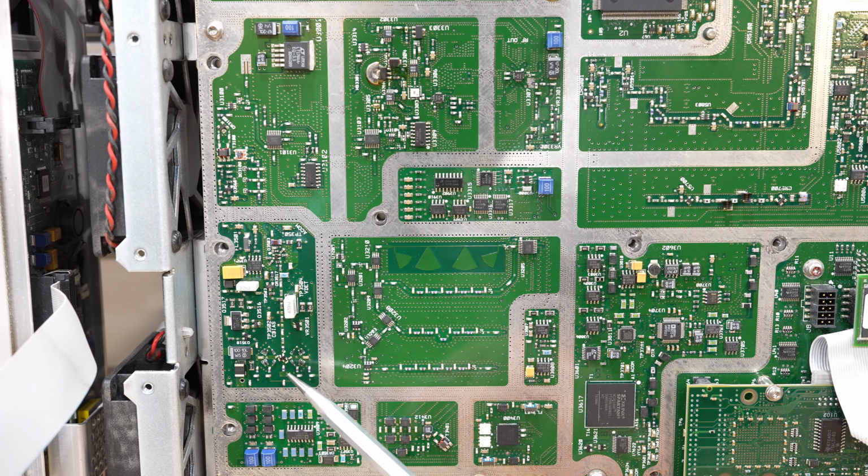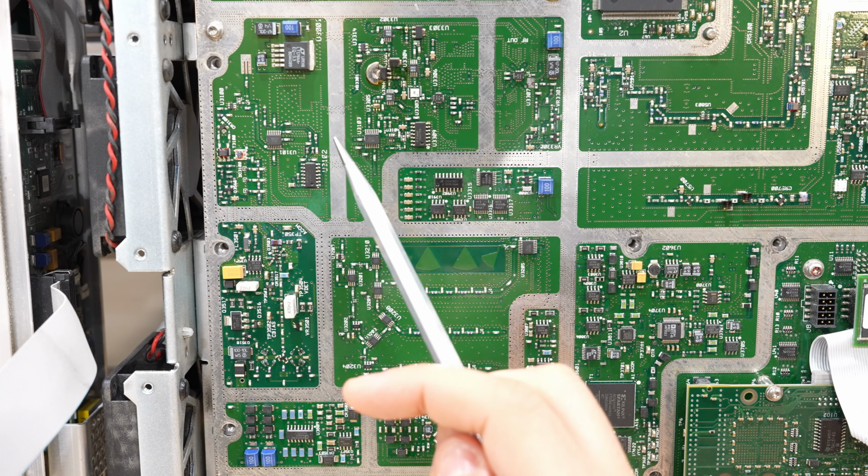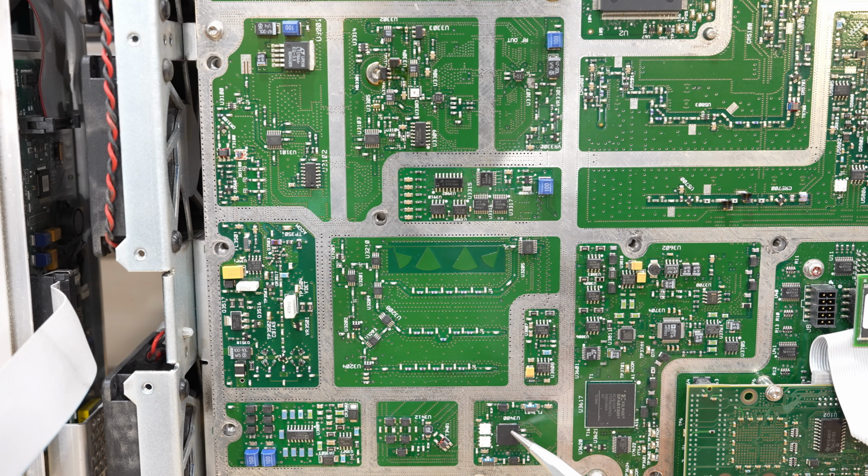So we have VCO, coupled path, doubler, bandpass filter selection with 2 switches, fed back, input of the fractional divider controlled by the FPGA, phase detector with the 50 megahertz reference, and back into the VCO. And that's the loop we really should be paying attention to. Now what we can do is we can actually run this. Luckily everything here is on the top, and we can probe these different areas while the loop is working and convince ourselves that these signals really are where they are supposed to be and they do travel through this entire path. That's pretty easy to do with an active probe. So we should be able to make these measurements, and that really should be the first step.